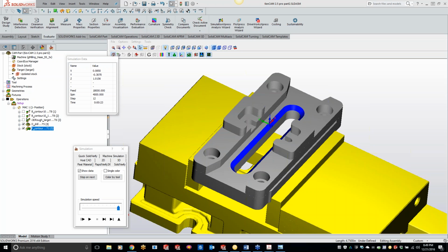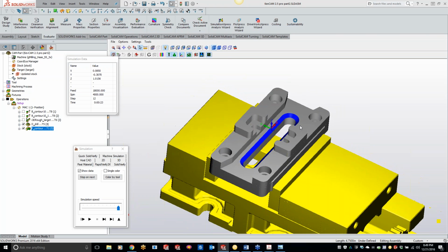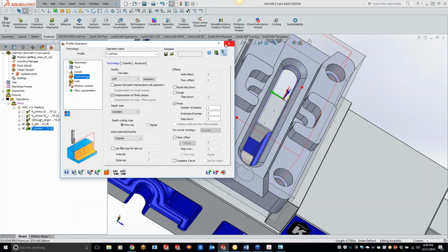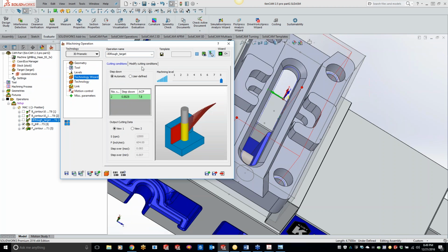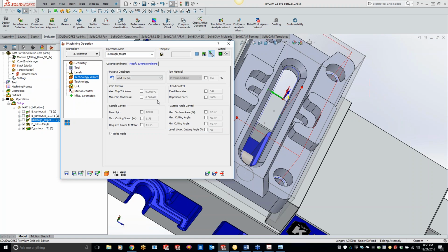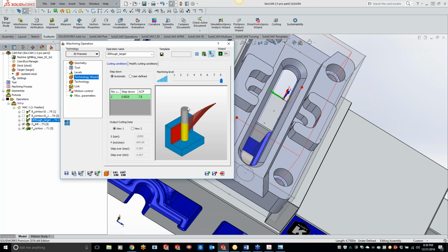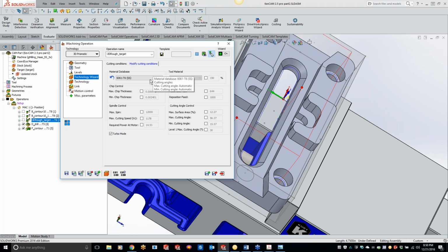Absolutely. Yeah, you have full flexibility. Now, let's say we go into the die machine, I want to control it. We're not locking you guys out of anything. Maybe I want to do a different chip thickness. I can turn this on and do a smaller or larger chip thickness. Maybe I want a faster feed rate. It's all right here for you guys. We have the wizard set up so it automatically calculates feeds and speeds. If you're not happy with those, or maybe you just want to change up your chip thickness a little bit, it's all right here for you.